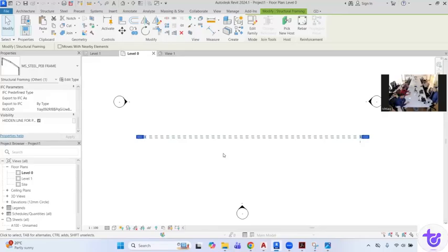But if there is a certain requirement and you cannot change the detail level of a view, and it is recommended to use the fine detail level in every view, some constraints are there. Then you will have to stop playing with the visual styles. That is not good. This one, the subcategory, is better. Subcategory will be a good solution for this kind of thing. This is applicable for all families, wherever you want, you can create a subcategory.